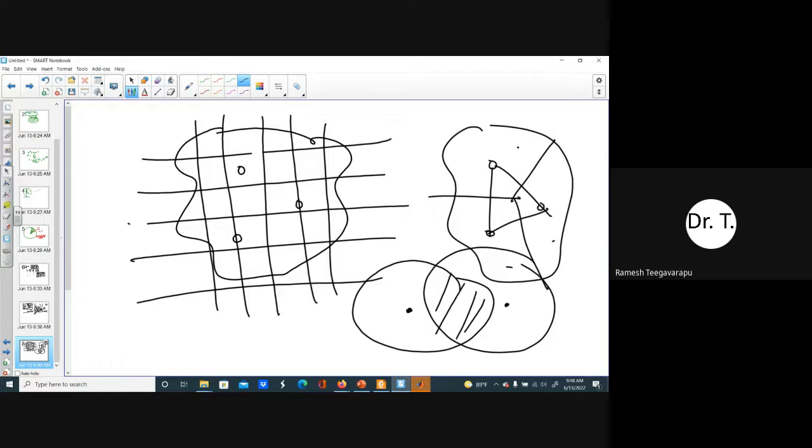In the case of urban rainfall, the rainfall is not based on S-band radars in many countries. They use X-band or C-band. These are smaller wavelength radars. They can be installed on top of a building. The advantage is that their strength is smaller and their range is smaller, but they are very accurate. Sometimes you can even put one on top of a car and try to get rainfall very quickly, especially in urban settings.